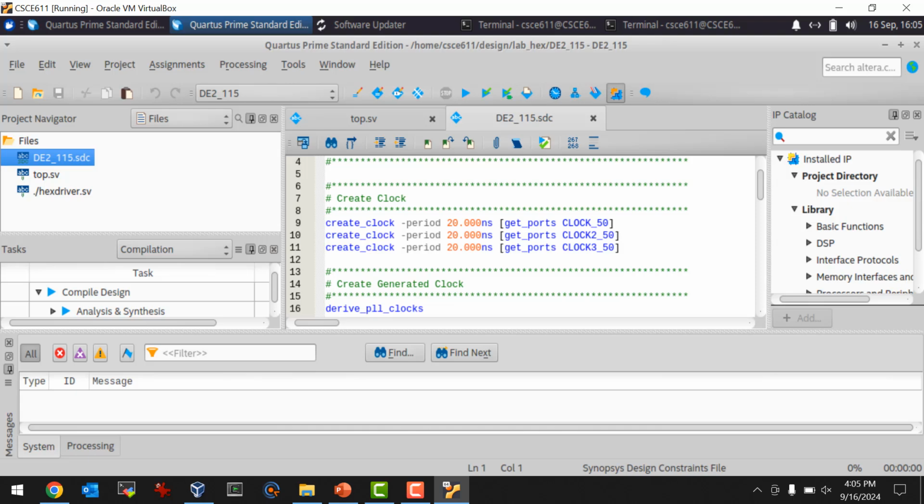So when it synthesizes the design, it has to guarantee that the chip will operate at that clock rate, even if you're operating it in your oven. It's doing a worst case analysis over different temperature ranges and different device variations. Okay.